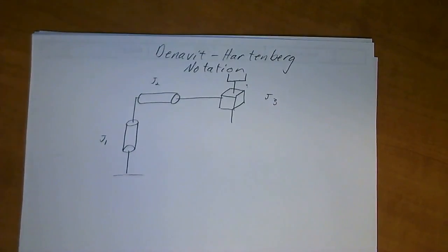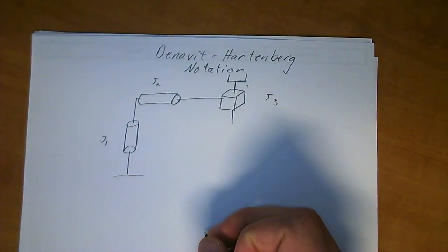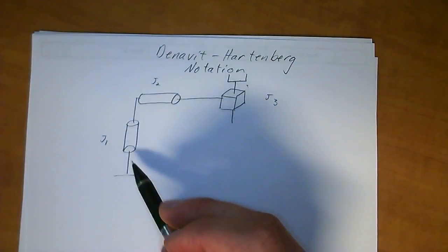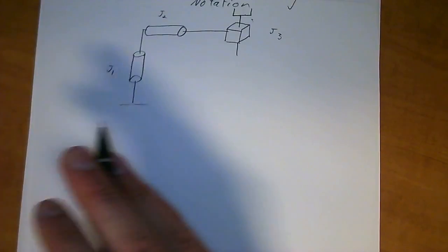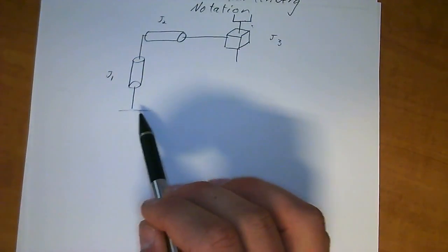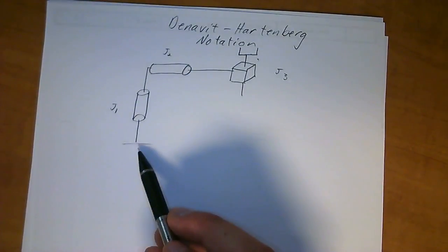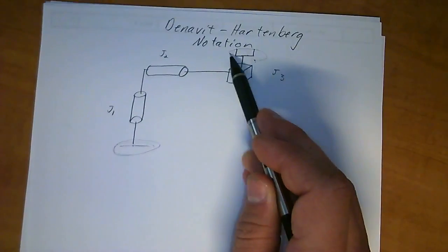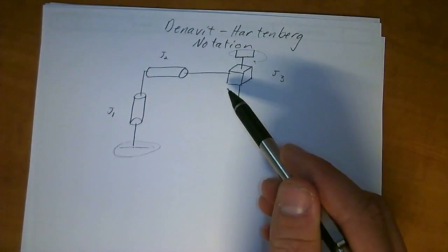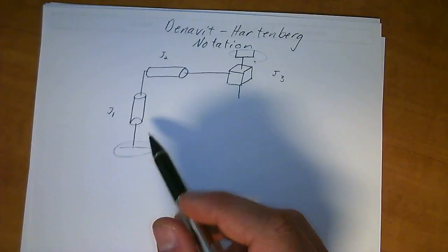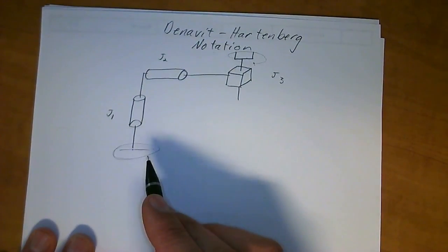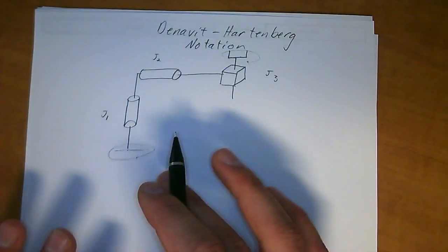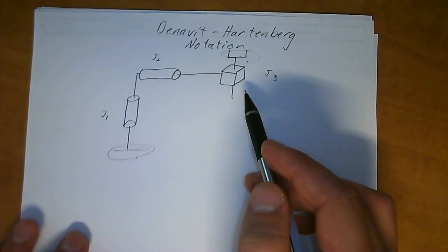everywhere. Okay. So DH notation has several rules, and actually exactly 7 rules of how to define each one of these joints as you're going through them. So it can get a little bit hairy, but just to get this cleaned up right off the bat, in order to make DH notation work, when you're using DH, you do not consider the base or the end effector axis as they stand right there. You only consider what's happening in the joints. So that's something you can eliminate right off the bat, and you would calculate it later using traditional forward kinematic equations. But in order to get what DH can give you, you have to focus only on the joints.